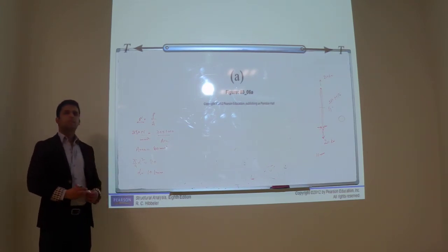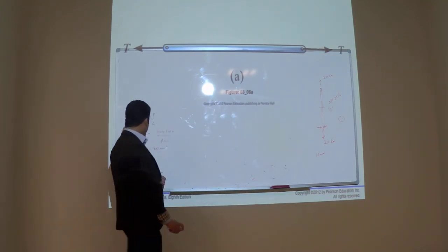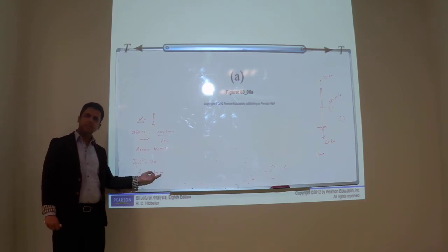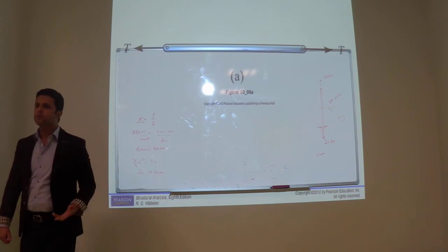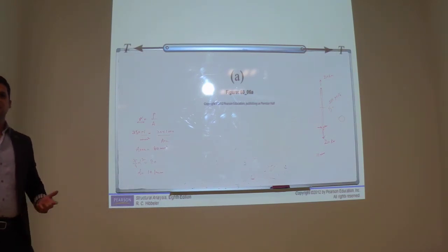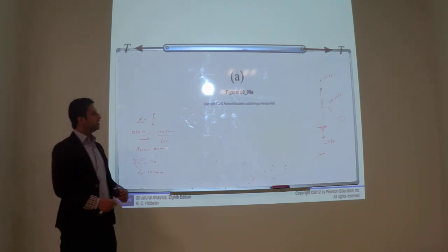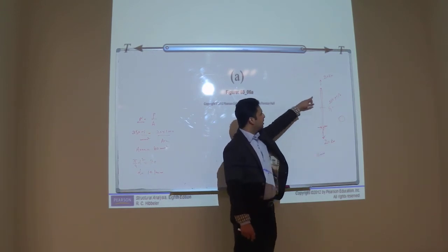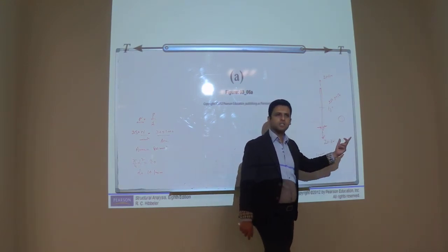So it means if you want to resist this load, this is the minimum diameter of the bar which you have to provide. If the bar diameter is greater than this, you can resist that load. This is known as design. What did you do? You just found the required diameter for a given load. So what type of load is this? Tension load.